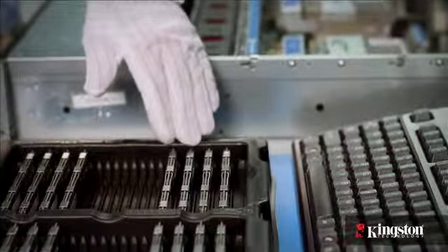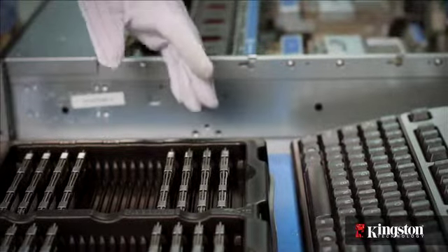Next, select the first group of 4 modules to install in the white memory sockets. For best memory optimization, you'll want to install groups of 4 identical modules in each memory bank. If you're working with memory of different types or different capacities, such as memory that came from the factory, you'll want to keep those modules together.